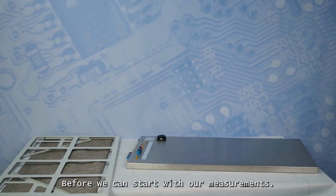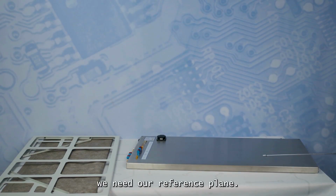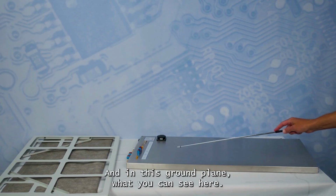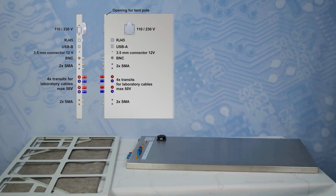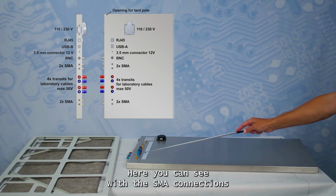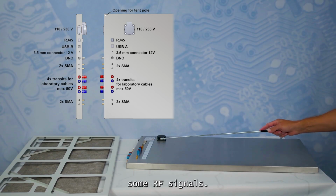Before we can start with our measurements, we have to set up our shielding tent. Here we need our reference plane, this basic ground plane. And in this ground plane, what you can see here, we have different connections to the outside. We have, for example, RF connectors. Here you can see the SMA connections to put some RF signals to the outside or also to the inside.